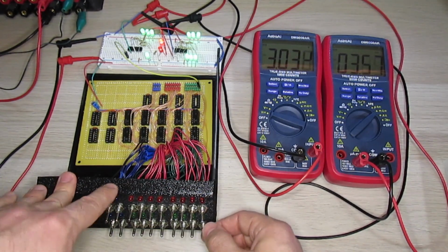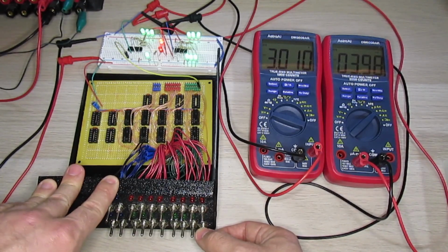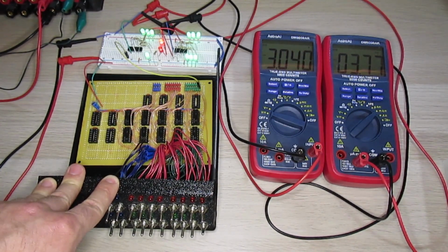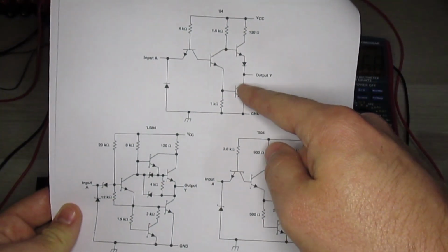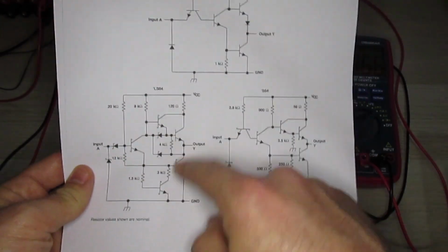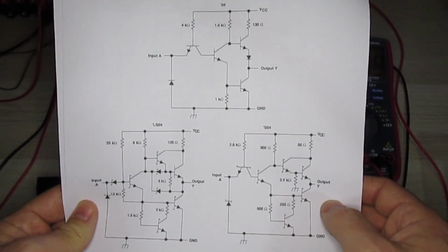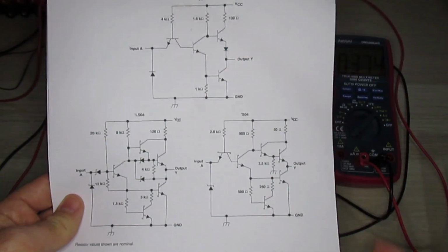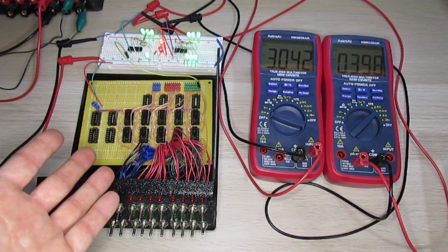So I think the moral of the story here is that even if you have some pretty insane small resistor values, and you push these chips outside of the datasheet ranges, everything still more or less will probably work okay in most cases. Of course, this was specifically with the 7404, and there are also different flavors of these chips. There's the 74LS04 and the 74S04, and they all have different input and output circuitry, so they're going to behave a bit differently. And also just from one part to the next, they could vary, or from different manufacturers or different batches, so we're still not guaranteed to operate correctly. But for the most part, it's probably fine.